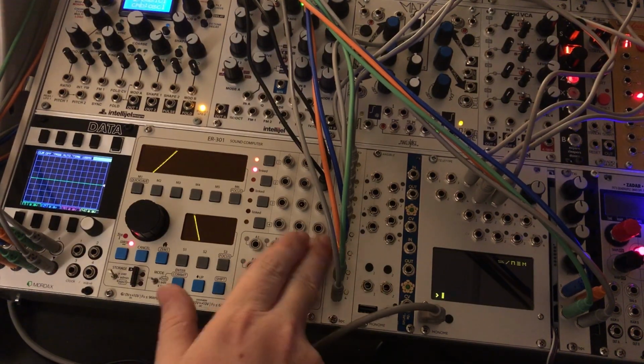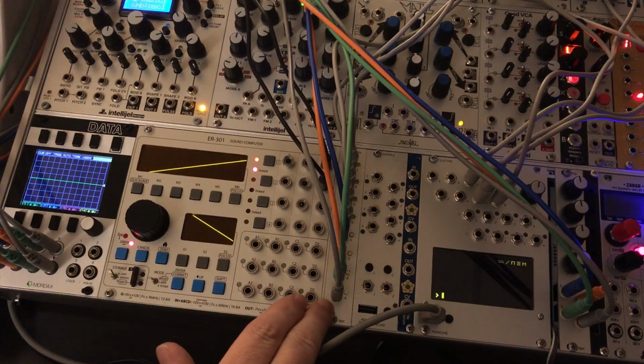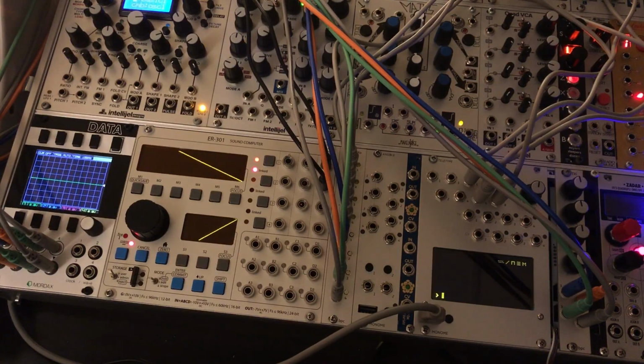So the Teletype output expander CV ports are capable of a bunch of different things, actually. They can output DC voltages. They can output waveforms at very, very slow rates into the minutes or hours, and they can oscillate so fast that they can become sound sources as well. They're also capable of generating attack decay type envelopes, and they can even do some of these things at once. So you can even have enveloped LFOs or enveloped audio rate oscillators.